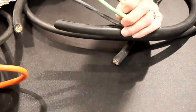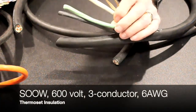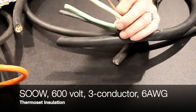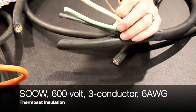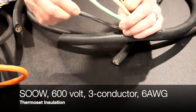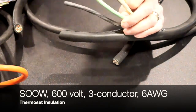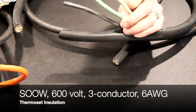It also tells me in the table that this particular SOOW type cord is available in gauge sizes 18 up to 2 gauge. It may have 2 or more conductors inside the flexible cable. It is a thermoset type of insulation over the conductor material. Keeps it very flexible, by the way, as opposed to a thermoplastic we'll look at in a minute. And then it gives me the dimensions for the different gauge sizes.